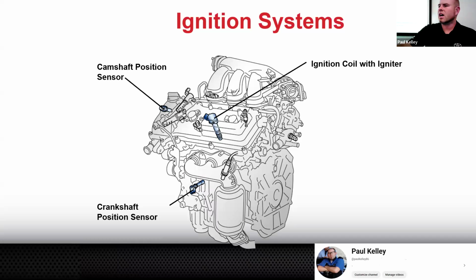And she was like, it's got to be the spark plug, right? Because I moved the coil from 3 to 5 and it didn't follow. The only thing left in that cylinder is the spark plug. And I was kind of like, cool idea, but what's the holdup? I can't get the spark plug loose. I need a longer ratchet. And I'm sort of like, all right, let me be a little more harsh, but also helpful.